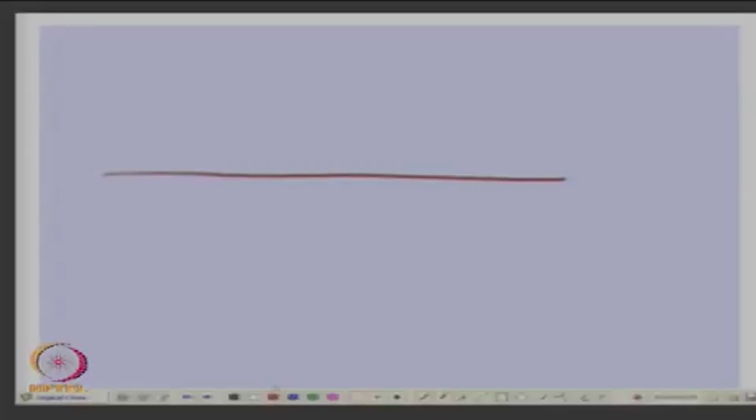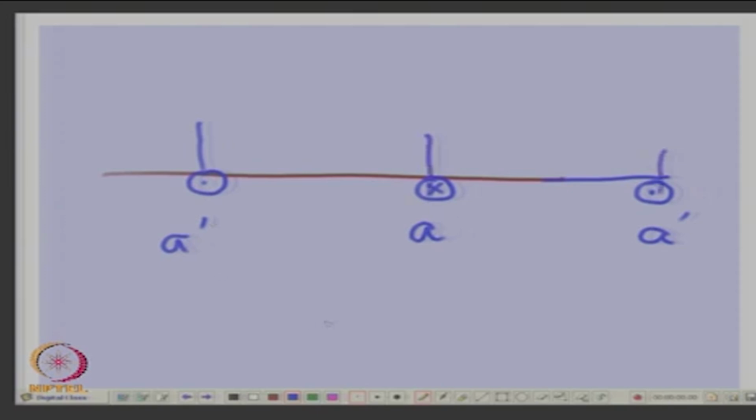See, harmonics in MMF wave, right. Suppose you have a conductor, a coil which is placed like this, A, A dash. If you have just one conductor, the MMF waveform may be squarish or rectangular, because flux lines will go round like this.